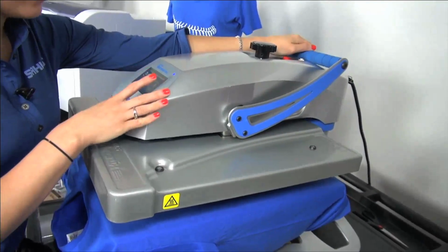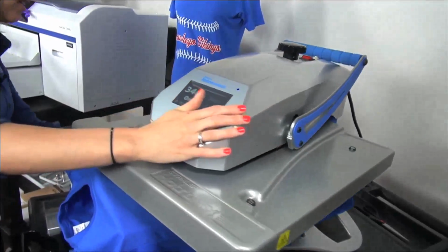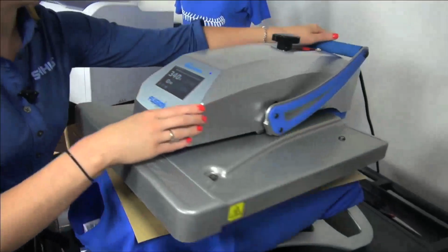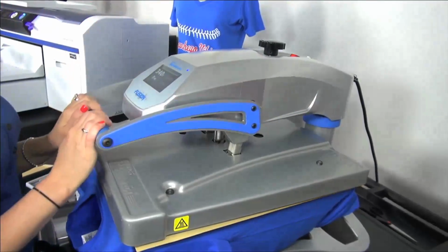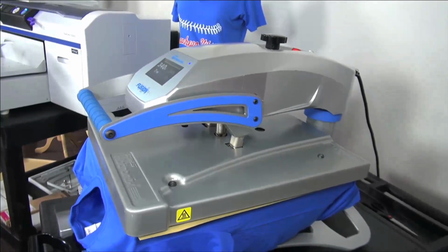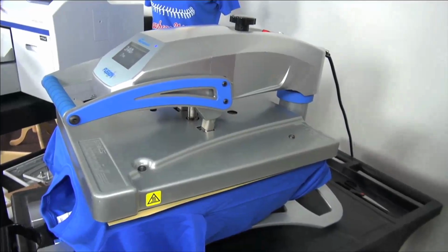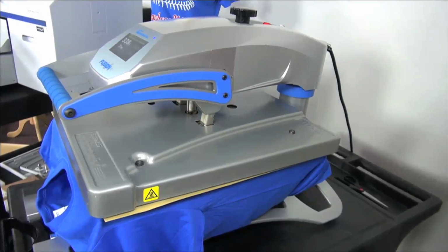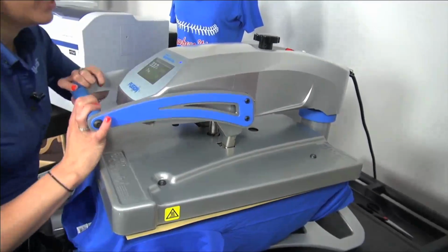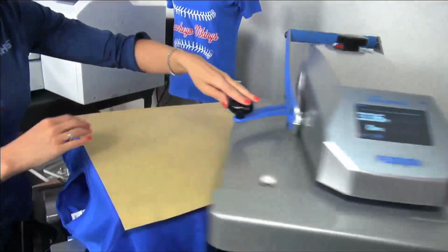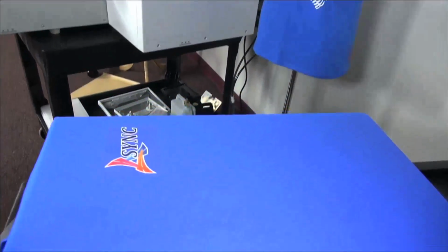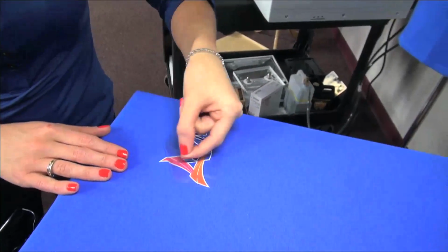This heat transfer applies at 340 degrees for 15 seconds. I am just going to cover it to protect my carrier, which is a little bit of a thinner carrier. For those of you that have solvent ink printers, which I think a few of you here attended the class today, this would be the type of print transfers that you can print on a solvent or an eco-solvent printer if you wanted to begin printing these types of transfers in-house. Once that application is complete, I can peel back my carrier.